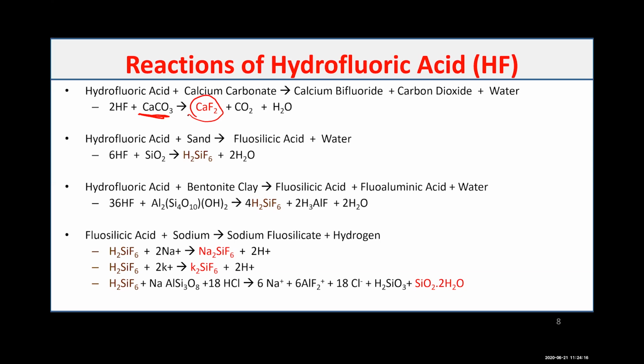And that's like a cut-off point for us. If you have a formation, even a sandstone formation, that has a high calcium carbonate content, usually people say above 20%, we never bump HF, because you will have a calcium fluoride precipitation that significantly reduces the porosity and permeability. And instead of having enhancement, you're most likely increasing your damage. So you do not bump HF in a formation that has a high calcium carbonate content, or definitely a carbonate formation. However, if you are bumping a formation that's pure silica or really high content of sand and clay,